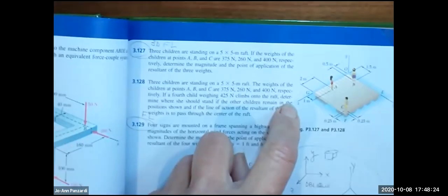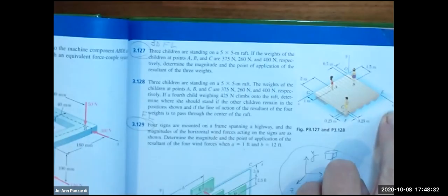Yes. Keep going, Myra. Positive or negative? It would be negative. Fingers in the direction of the force, palm towards z. Did you get positive or negative? Negative. Great. And how about x? Do they create a moment about the x? A positive one. A positive moment about the x.